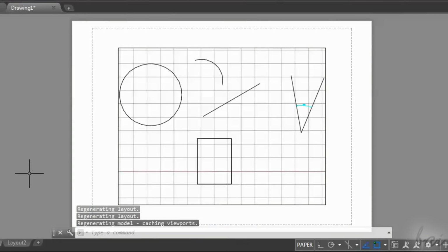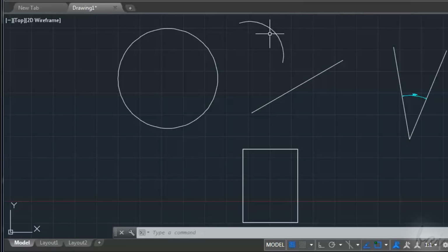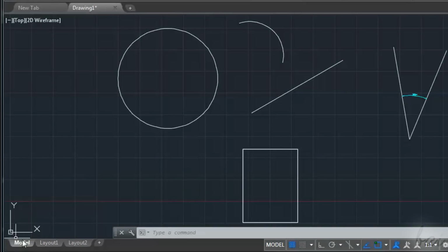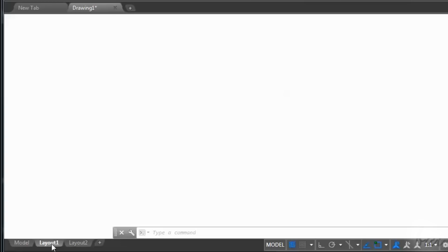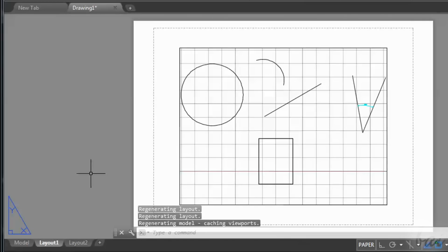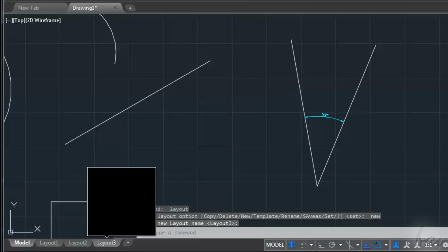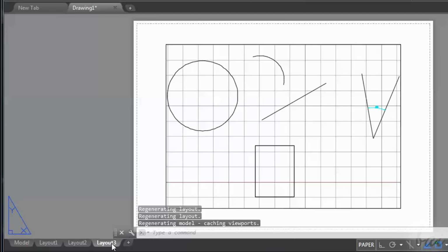In AutoCAD, it is also possible to make 2D layouts. In the bottom left corner, you have two main tabs, the Model and the Layouts. The first one is your current project, while the second ones show how your current project is, for example, after printing. Let's suppose you want to see how your project can be. Set your favorite point of view in 2D or also in 3D. Then press on the plus. This creates a new layout referred to your project at the current point of view.